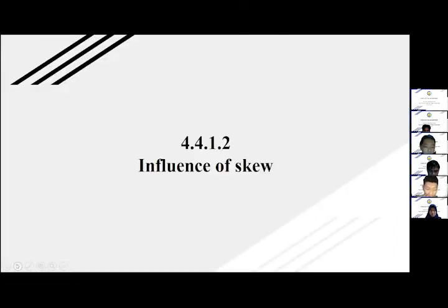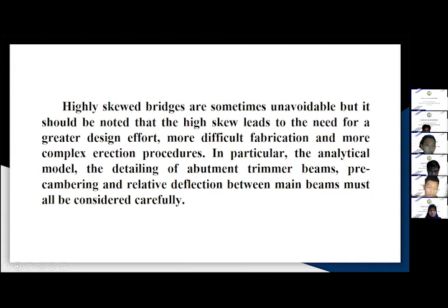Influence of skew. Highly skewed bridges are sometimes unavoidable, but it should be noted that the high skew leads to the need for a greater design effort, more difficult fabrication, and more complex erection procedures. In particular, the analytical model, the detailing of abutments, trimmer beams, pre-cambering, and relative deflection between main beams must all be considered carefully.